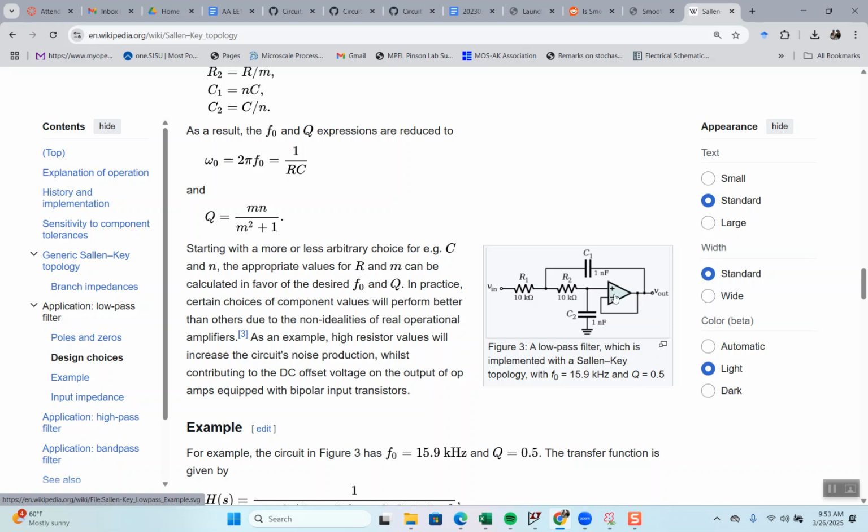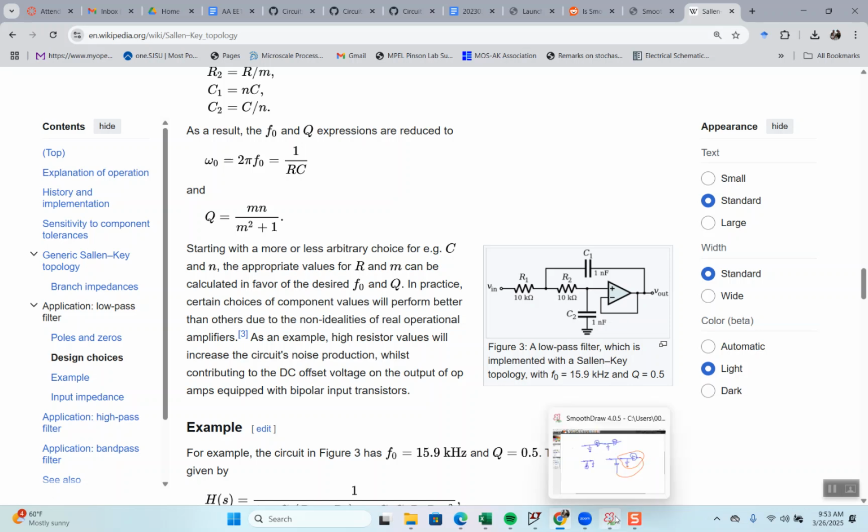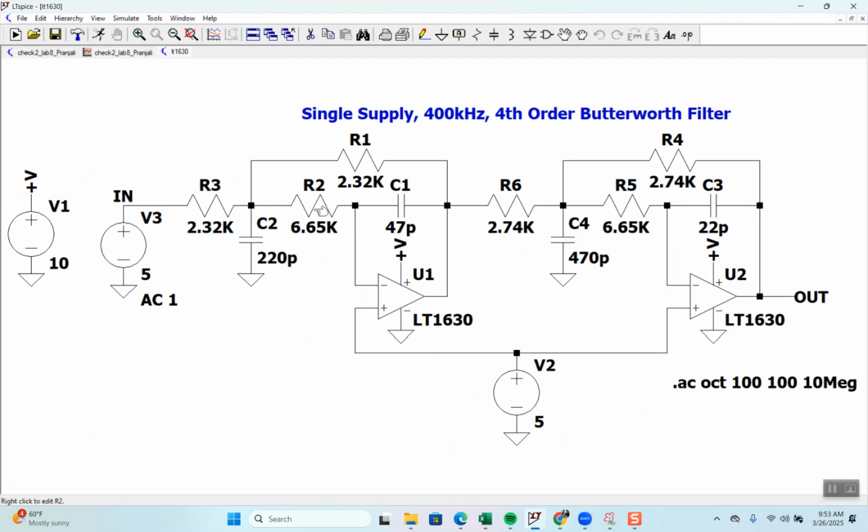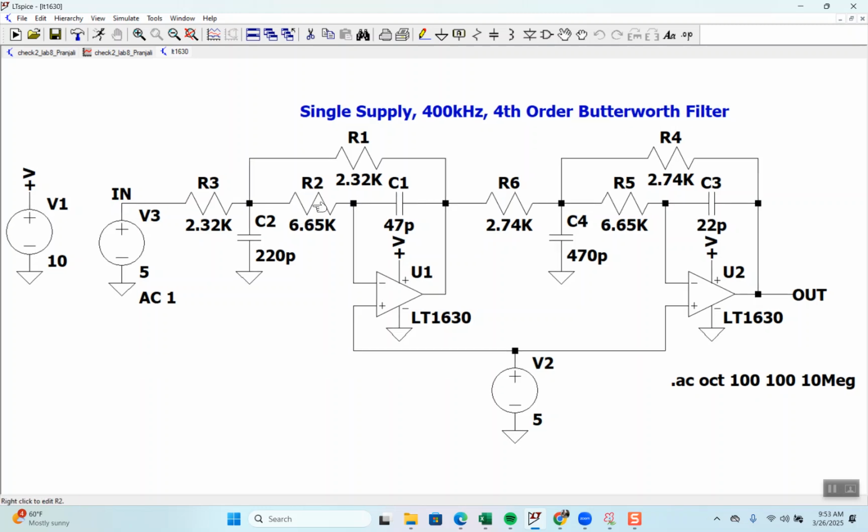And the fact that that's a buffer causes this circuit to stop working or have unintended consequences, compared to this, which is from here to here, right? It's an inverting amplifier, right? And with a capacitor in the feedback loop, it works for a longer period of time, okay?